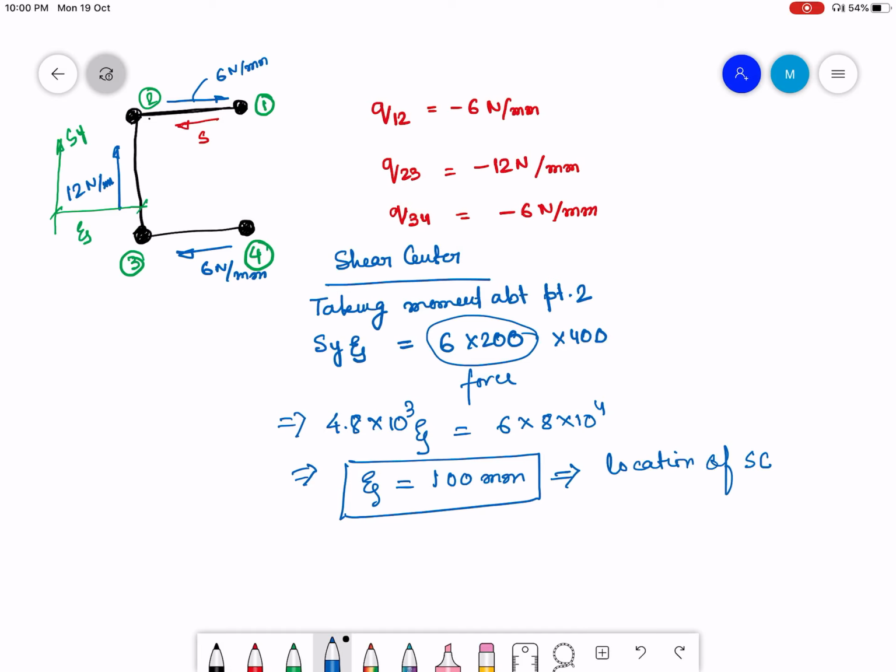One thing I want you all to note is the main difference between finding the shear flow for the actual cross section and for this skin stringer idealized cross section. For the actual cross section, the shear distribution would have been a certain function. We have already done this problem before. If you remember correctly, the shear flow for a C-section was of a parabolic shape, something like this.